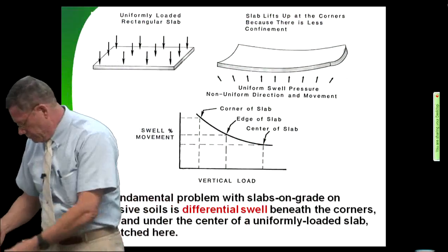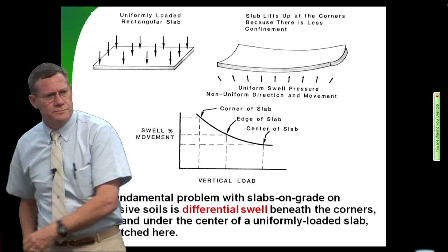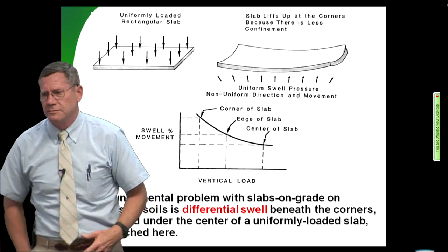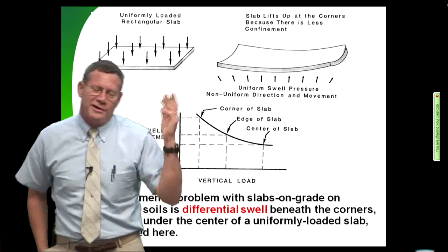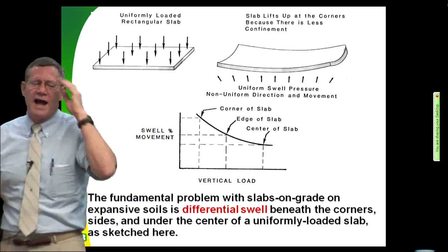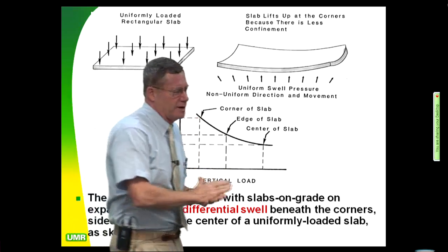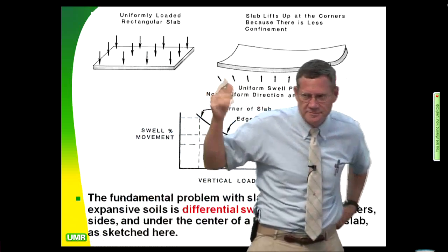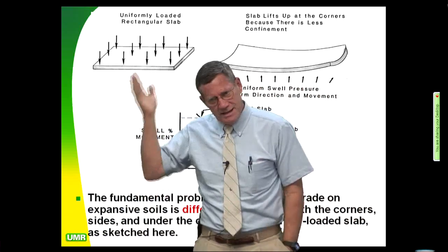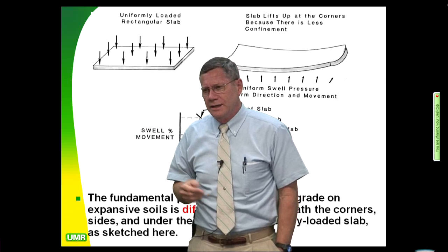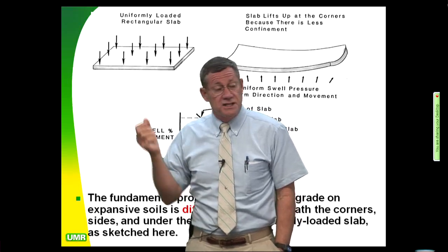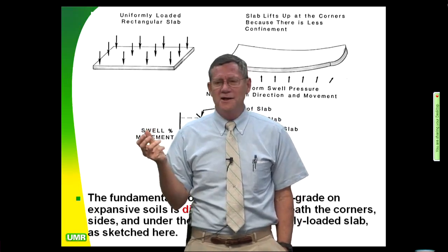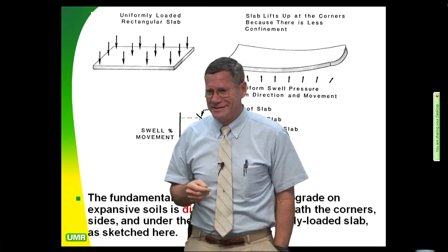Now, if we had the basement of a hospital, what do they keep in hospitals? Well, yeah, morgue too. Yeah, the morgues don't weigh too much. No, file cabinets. What do you think file cabinet bearing is? Want to hazard a guess? Ten times higher, about 300 pounds per square foot. So that's the biggest load you design for until you do a paint factory.